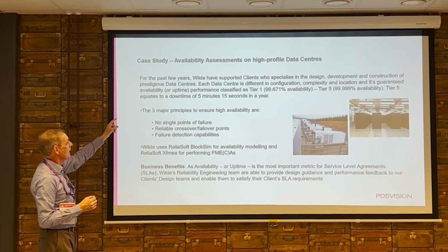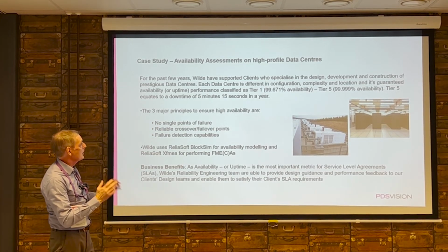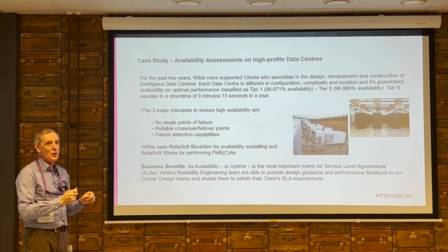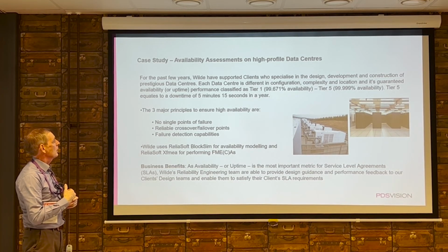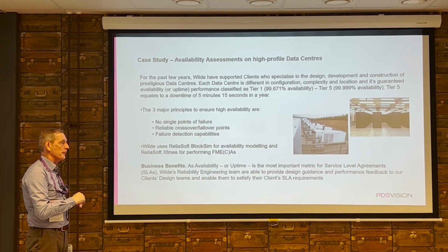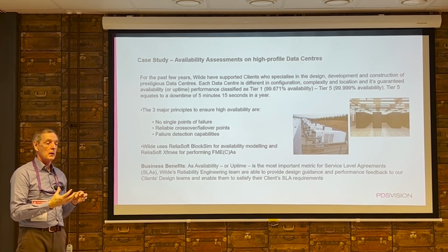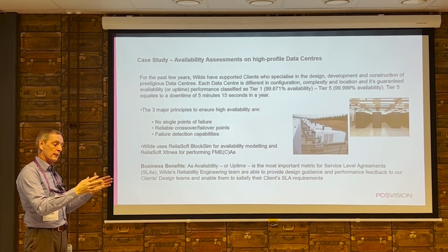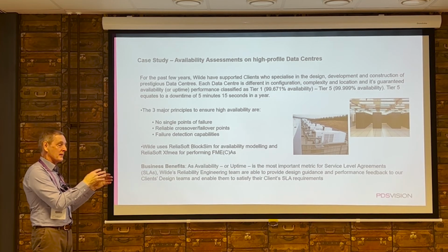And you can see here, tier 5, which is getting more and more common these days. A tier 5 data center means that in a year, for maintenance, it can only be down for 5 minutes and 15 seconds, which is no time at all for doing anything. You can only get your spanners out in a couple of minutes. So you have to remedy this by having a lot of extra redundancy built into your system. So rather than having one generator, you might have 4 generators. And you might expect that in a typical year, 2 of those generators might fall out, but I've still got 2. So that's how you achieve your availability calculations.